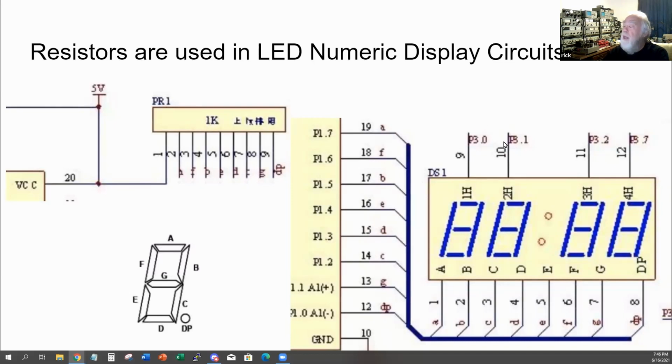So if you just connect one of the digit leads to your negative supply and allow this resistor pack to provide positive to all your segments, it will light up all 7 segments and the decimal point segment. So it's the purpose of these lines here to actually write a 0 bit or pull down to a 0 logic level the segments that you do not want to light, and allow this resistor pack to light the segments that you need to illuminate when the digit signal is set to a negative signal by another port in the processor.